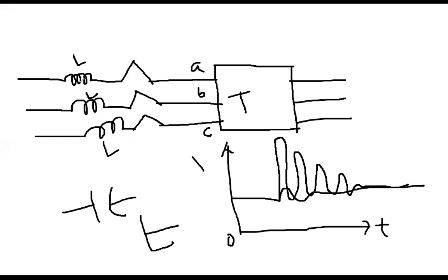And in this case, we are using the inductor to work as a limiter, to work as a transient mitigator, for the decay component. Because through an inductor, current cannot change immediately or instantaneously. That's why it is safe. A little transient may happen, but it is not like that 8 to 10 times. So that's why this is highly recommended. Before energizing a transformer, please use some small reactor. That is the meaning. Could you follow me? Yep, makes perfect sense. Yes.